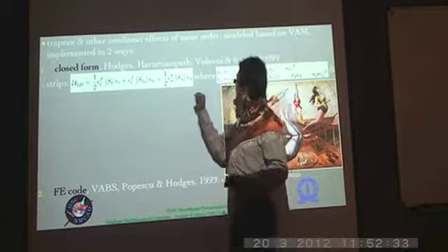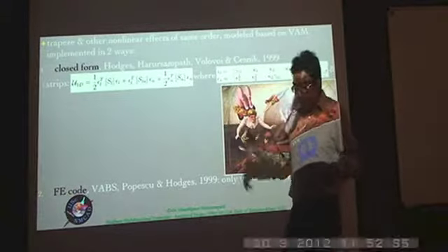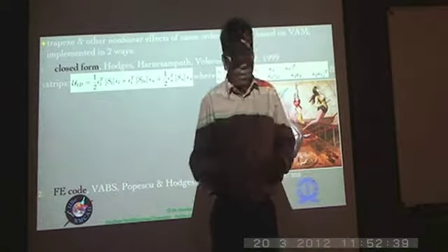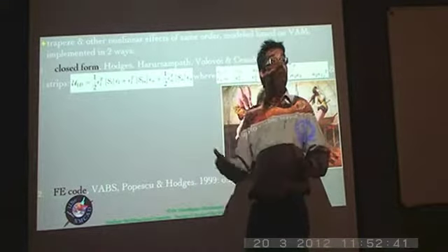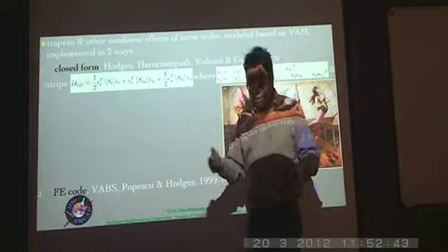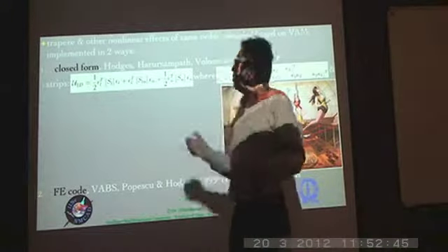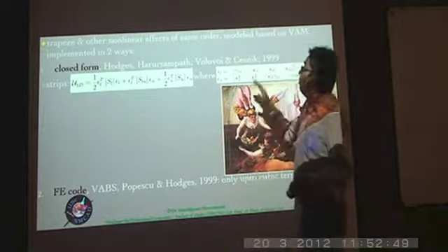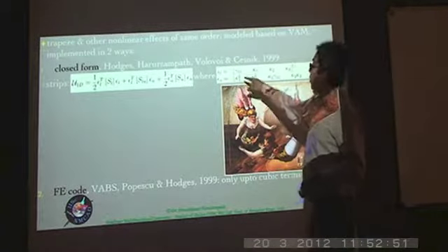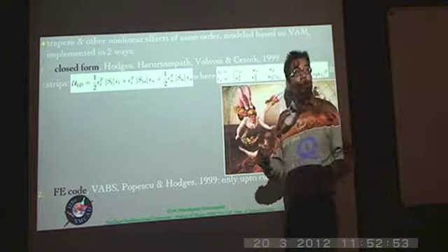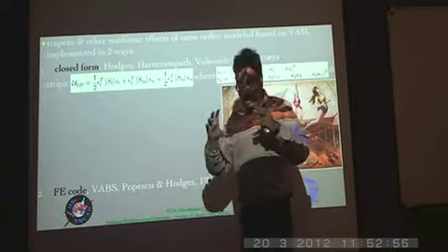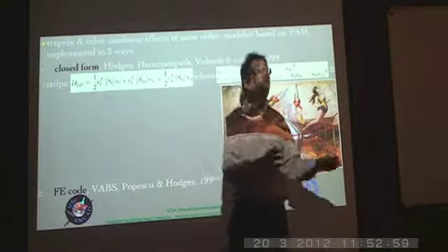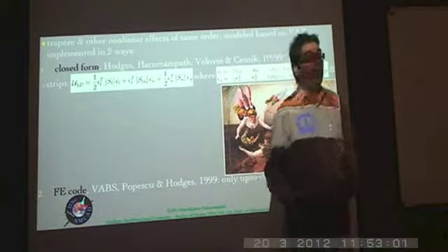So whether we take them into account or not, up to the first order approximation doesn't get affected at all. It's the second and higher order approximations which are engineeringly insignificant. So only in such situations do you really need to introduce them, because it's a thin strip. What is more important in a thin strip is the nonlinearities, whereas in a thicker beam the transverse shear effects will come into prominence and the nonlinear effects will go out of prominence.